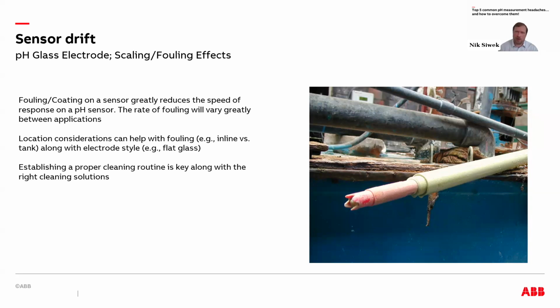Hydrochloric acid did not work in bringing the sensor back. It was basically unresponsive. And it wasn't until an HF-based acid for cleaning specifically was used that actually brought the sensor back. So depending on the right solution or what you use can make a world of difference in bringing the sensor back from the dead, essentially.